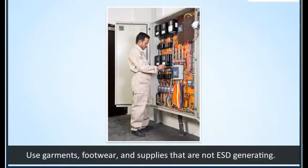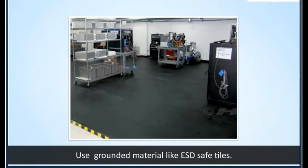Look for garments, footwear, and supplies that are not ESD generating. Use grounded material for flooring such as ESD-safe tiles.